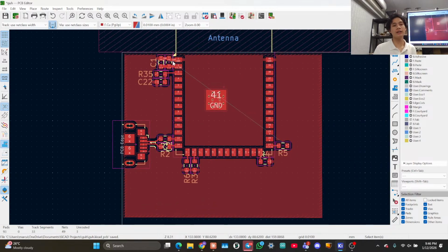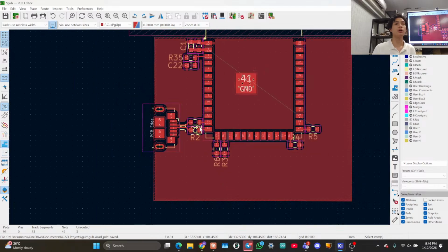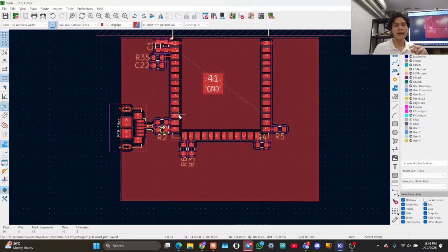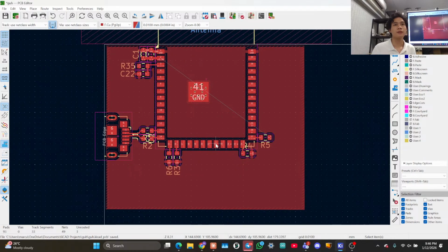So in our application, it's managed to connect from the other side, so we're fine. But sometimes you will have a copper pour and it will just fail to go through some areas. So you need to understand that a copper pour doesn't magically just connect things. Sometimes it has an obstacle and it just can't get through. So it's up to you to check whether your copper pour is actually connecting stuff together. Any questions about copper pours?